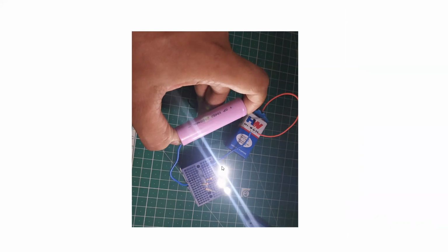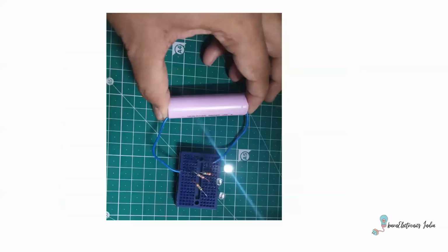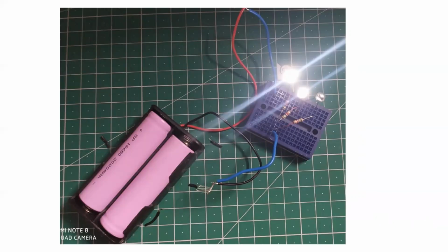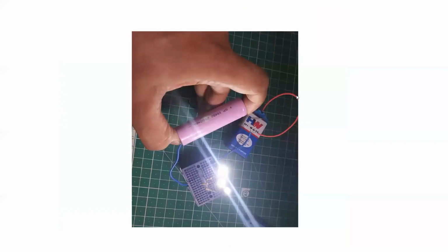You can even do it this way: you take a 9-volt battery which is at half of its voltage, having only 4 volts. When you connect it to the circuit, you can see only one LED glowing, just like this particular picture. When you connect a 9-volt battery having approximately 6 to 7 volts, you can see only 2 LEDs glowing. With that, you can know the particular voltage level of the battery and use it for your application, right?